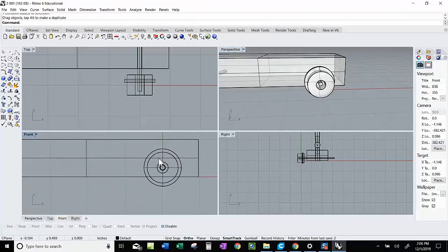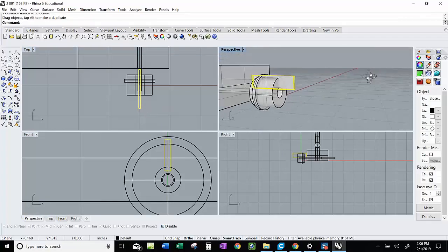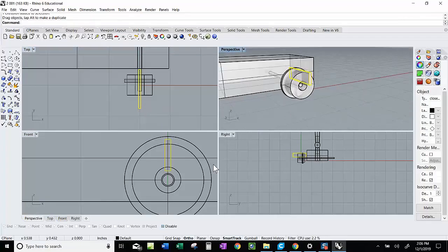So now, since I've got to do 6 spokes, I've got to cut the spokes out of this donut, and then what'll be left will be the space between the spokes, and I'll use that to cut the holes out of my wheel, leaving the spokes behind. So for my spokes, I'm going to use boxes, and they need to extend farther than the donut thing. So they're going through that.